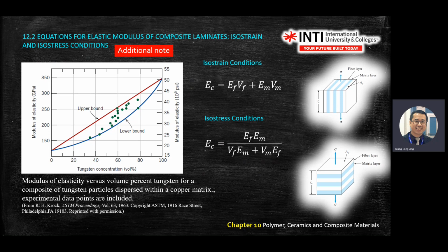So when you buy a composite, normally they will show you these experimental properties. They'll give you that material chart. They will show you the upper bound and lower bound. This will guide you on how you place your sensor. Because if you want to place a sensor on the vessel, on the container, you have to know the orientation of your composite.